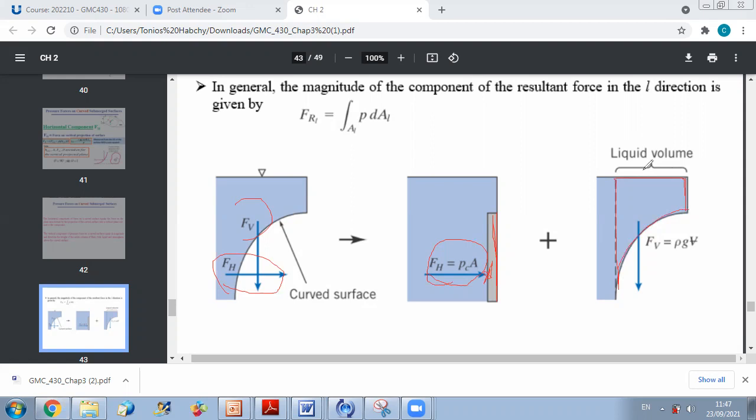And of course, we can neglect the atmospheric pressure effect compared to the weight of the fluid, especially when we have water and fluids with high gamma. Now, in case we impose any high pressure here and want to take it into account because it's not negligible, then we should find the total force acting on this part. Okay.